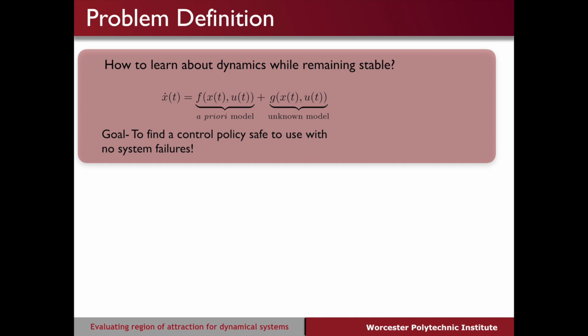For this, they start off with a small region of attraction around the equilibrium point denoted by S0, which stabilizes the system in a small subspace, and then we can learn the dynamics of our model. As we gather more and more data, we update the estimate of the safe set and expand and iterate this process of learning. We eventually explore the region and we get the maximum safe set. Lyapunov stability is used to find the solution and give a stability certificate to the model.